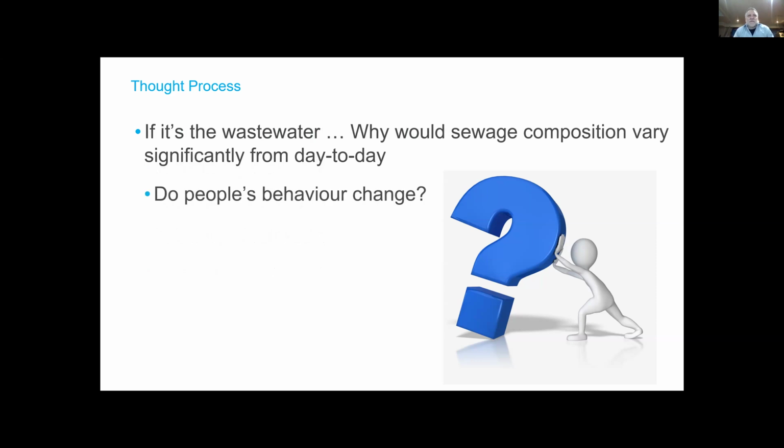If we think about it, do people's behavior actually change from one day to the next? I've been to treatment plants where I've done diurnal sampling years apart, and the diurnal pattern is identical. So we know from experience that people's behavior on average doesn't really change all that much. Yes, it changes slightly from day to day, maybe. And yes, behavior on the weekend is not exactly the same as on a weekday. But for the most part, people's behavior on any given day doesn't really change. And similarly, industrial processes and industrial wastewater don't actually change all that much. Sure, you may have a process that every Tuesday they do something and so on. But on average, over the course of a regular week, these things don't really change very much.